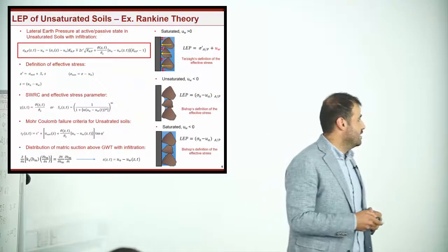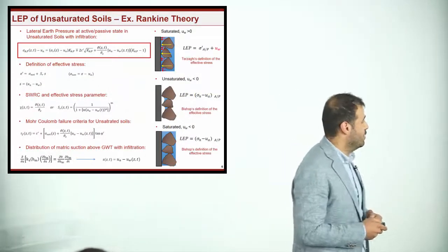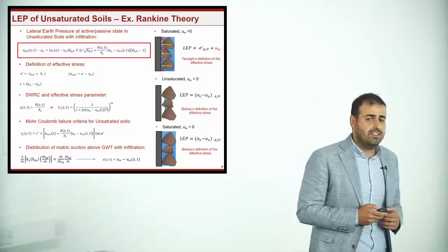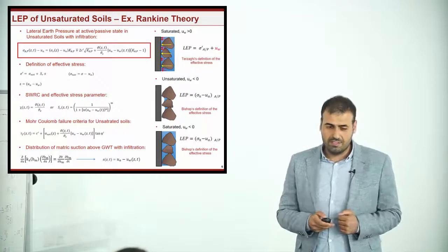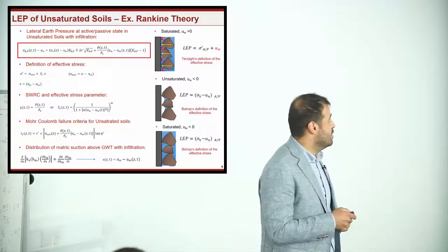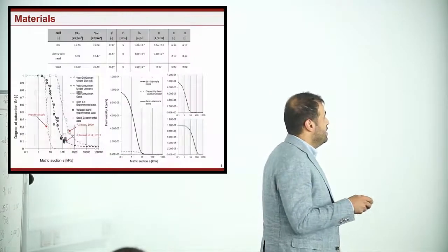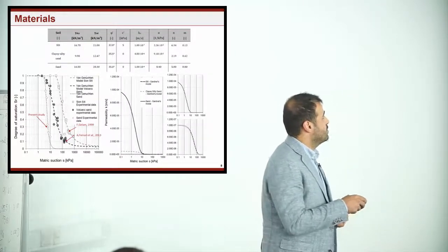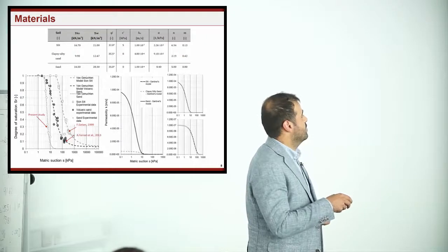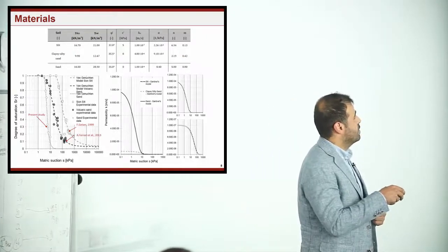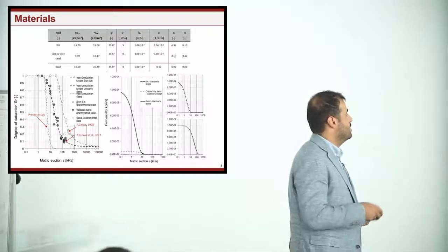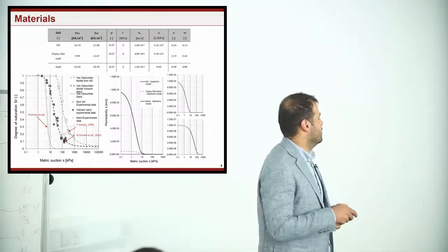We have the analytical analysis. In the literature we can find the extension of the Rankine theory, considering the mechanics of unsaturated soils, by performing also seepage analysis. And we can see here that the water retention behavior plays an important role in terms of degree of saturation, in terms of volumetric water content, its evolution in space and with time, and the matric suction.